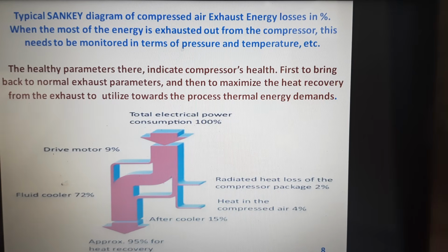How many of our plant maintenance personnel are monitoring the static pressure or the temperature at the exhaust duct? See, the exhaust duct, whatever the OEMs have given, let us size the duct correctly and dimension-wise, let us have the duct expanded in such a way that the air is taken optimally at a lesser static Pascal and the hot air is delivered outside. These are the healthy parameters that indicate the compressor's health.